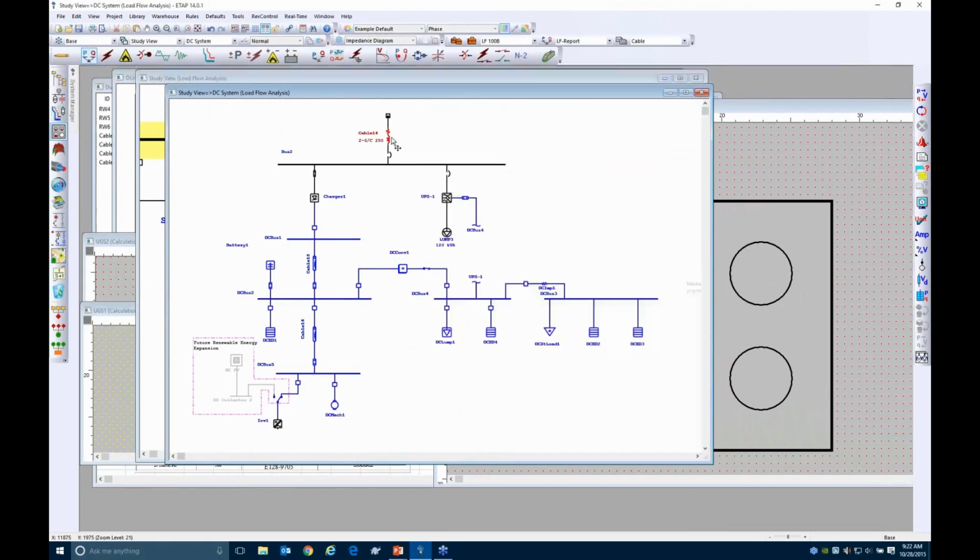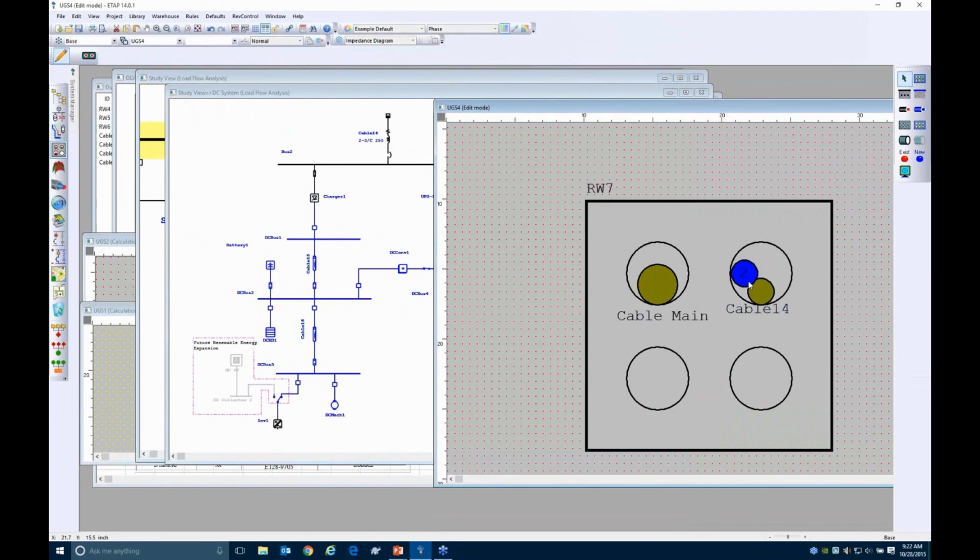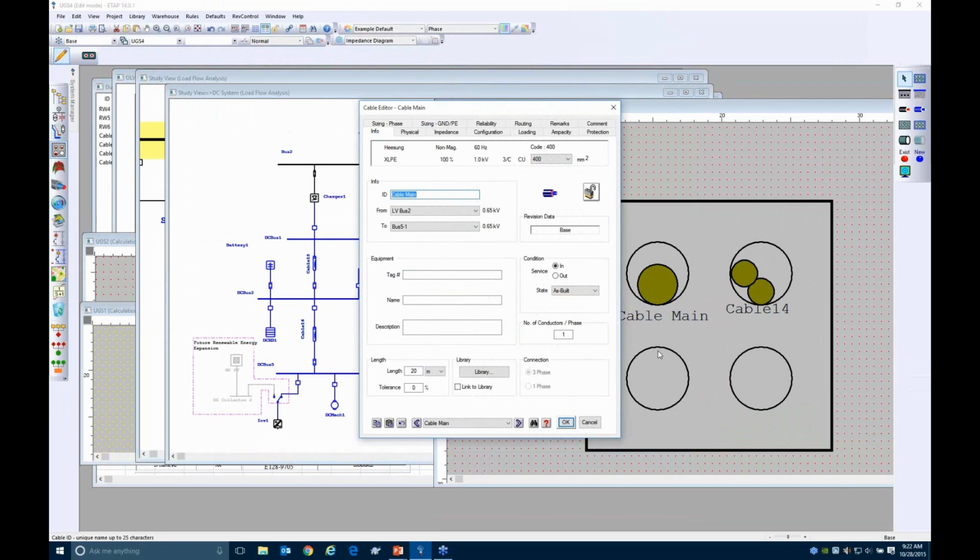On a side note, you'll notice that when I dropped this conductor in, it came in as two separate conductors, and this one came in as a single one. And the reason for that is this happens to be a 3-core cable. So phase A, B, and C happen to be within the same jacket or within the same insulation, and I have one of these conductors per phase. So I have a single phase A, B, and C buried inside this single jacket or insulation.